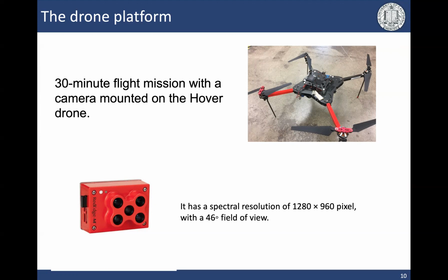The sensor also has a downwelling light sensor, which is a 5-band light sensor that connects to the camera. The RedEdge-M can measure the ambient light during a flight mission for each of the 5 bands. Then it can record the light information in the metadata of the images captured by the camera. After the camera calibration, the information detected by the DLS can be used to correct lighting changes during a flight, such as changes in cloud cover during a UAV flight.